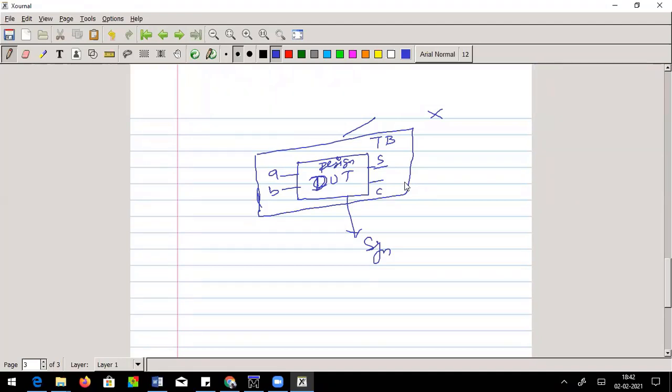That's what our whole idea is, right? And in the design, we followed one methodology: we deliberately said all our inputs should be wires, and outputs can be a wire or a reg. Now, for a test bench module definition,